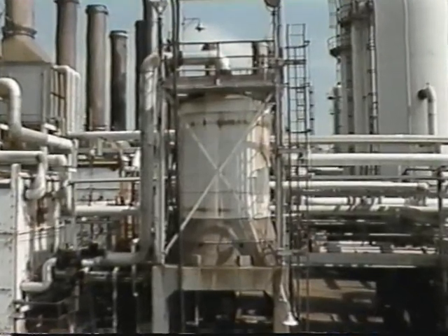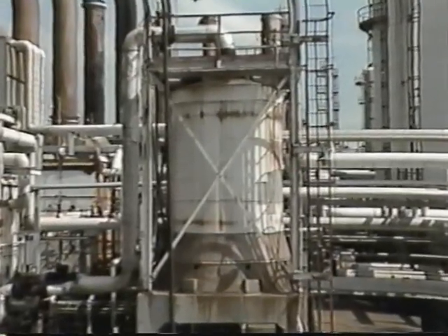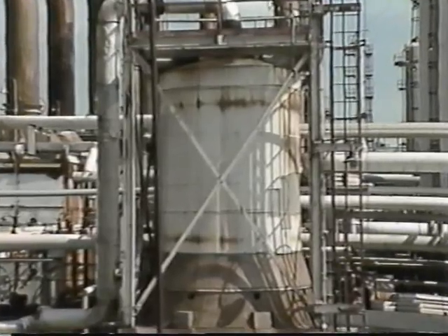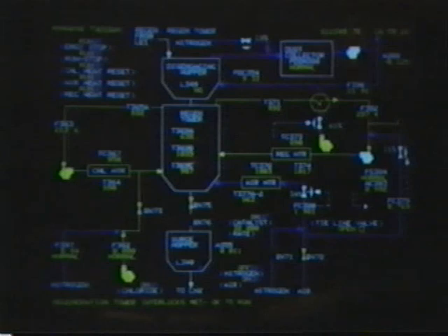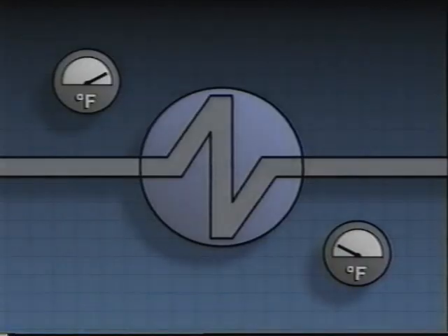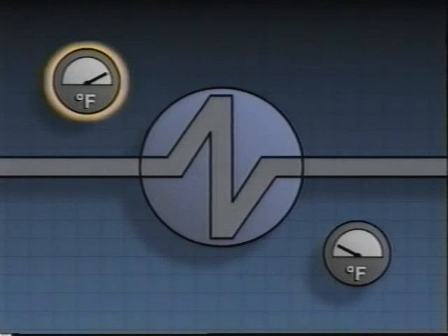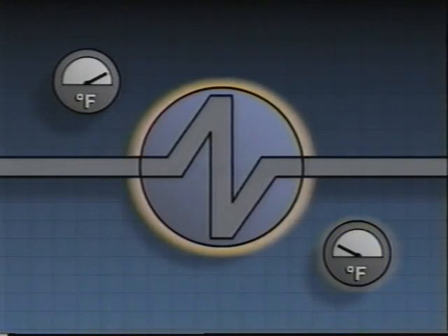One way to do this at the individual component level is to conduct simple input-output tests. As you know, most components in a process have process variables associated with them that allow you to monitor operating conditions. By referring to the process variable indications, you can check the condition of the process entering the component against the condition coming out. For example, if the inlet temperature to a heat exchanger is okay, but the outlet temperature is off, then there must be a problem in the exchanger.